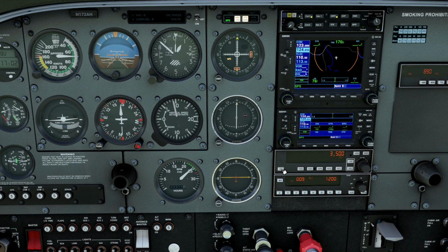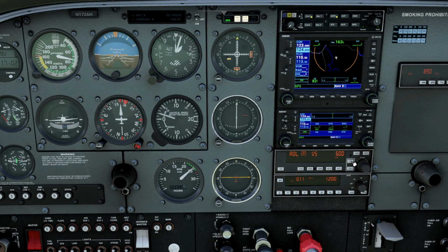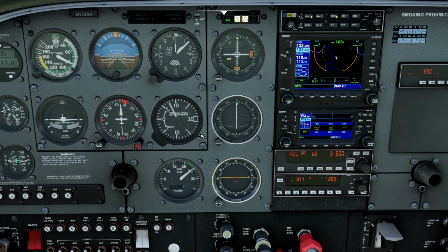If you want to engage your autopilot after takeoff or in a climb or in a descent, the way to do it is you hit the autopilot engagement button, and note your vertical speed before you do this. Hit the autopilot engagement button and then very quickly use your vertical trim buttons to select approximately the vertical speed that you were doing before you turned the autopilot on, and that should establish it in that climb, and will minimize the amount of time that you stop the climb.